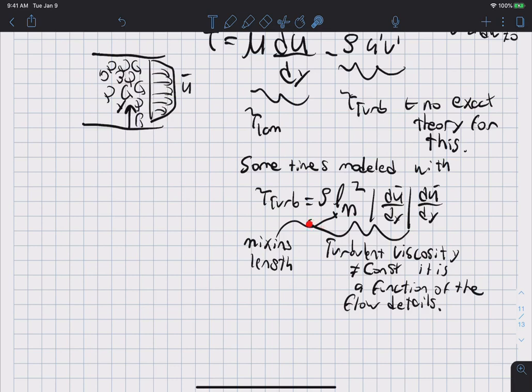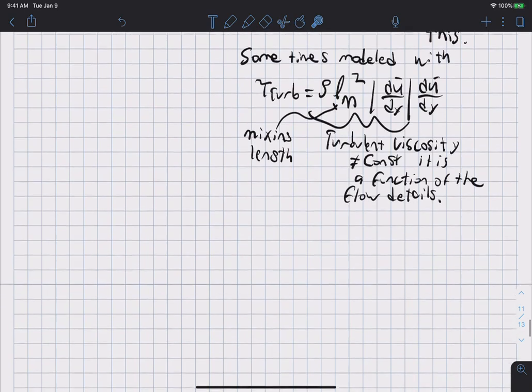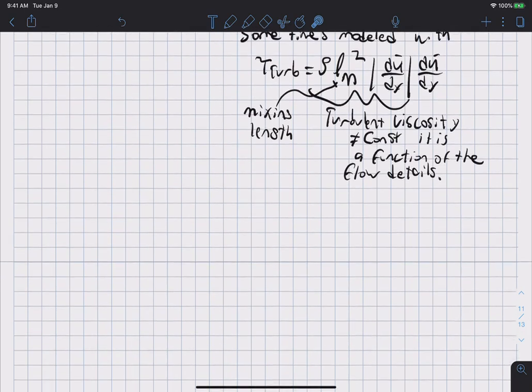And this is the simplest turbulence model there is, because even though fundamentally the turbulent shear stress depends on the jiggliness and the random fluctuations of the velocity field in the pipe, you are modeling those through rho times a length scale squared times the absolute value of the mean velocity gradient, and so the sharper the gradient, the higher the turbulent shear stress. And so this really increases the viscosity near the wall.